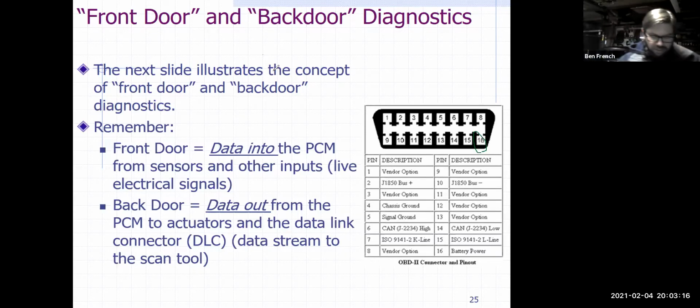Okay. So let's say you get this tool and you hook it up and you're not pulling data. You're like, oh man, what's going on? You know what? Go to the auto parts store with your car and have them do that free code read with whatever scan tool they have and see if their scan tool communicates with the car.